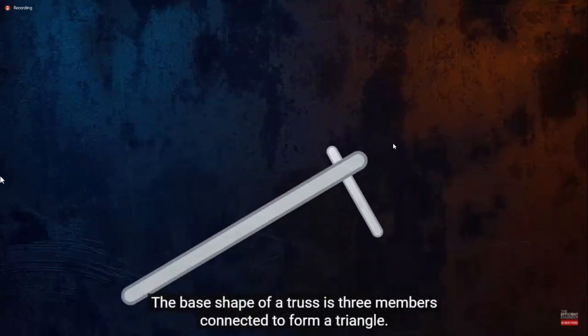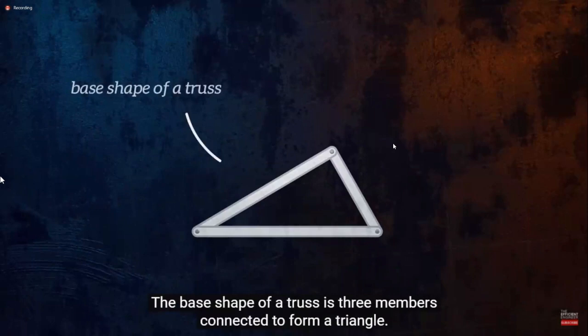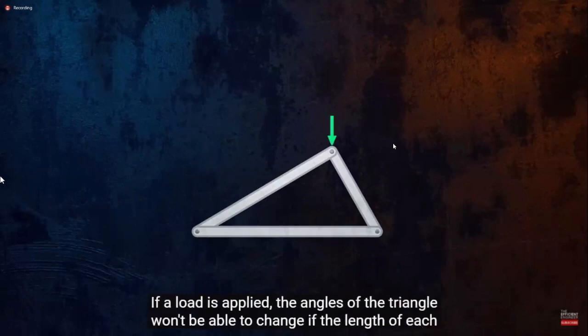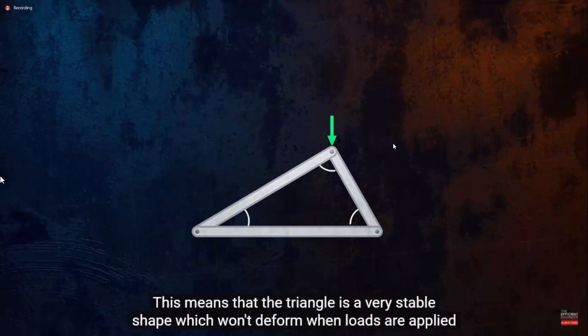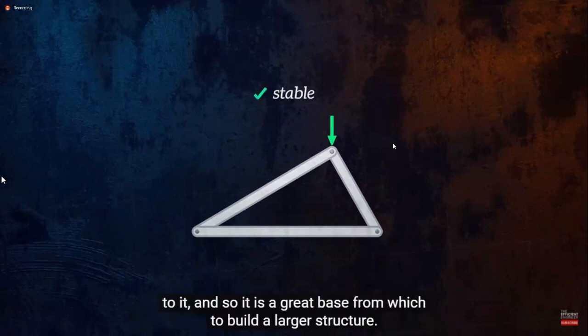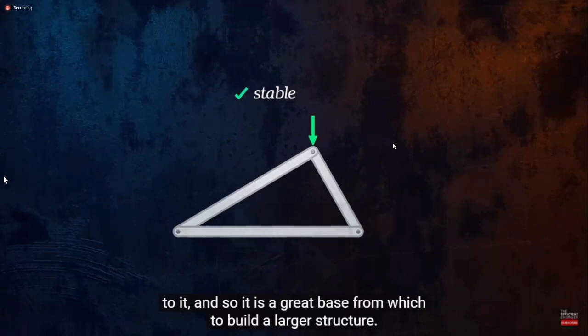The base shape of a truss is 3 members connected to form a triangle. If a load is applied, the angles of the triangle won't be able to change if the length of each of the members stays the same. This means that the triangle is a very stable shape which won't deform when loads are applied to it, and so it is a great base from which to build a larger structure.